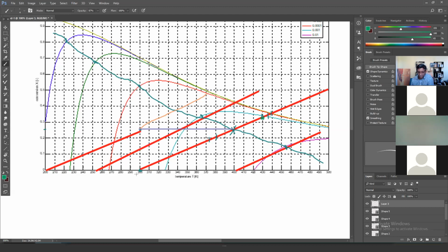So we know this line is supposed to be a CSTR, but if it had been a PFR, then we would say, okay, equilibrium is there, so 10K short of equilibrium is here. And so we can do that again. Here you can see the equilibrium temperature, and then 10K short of that is somewhere here. And then here, 10K short might be somewhere there, and so on. So in the same way that we drew the locus of points for the maximum rate line, we can do the same thing for the 10K line.